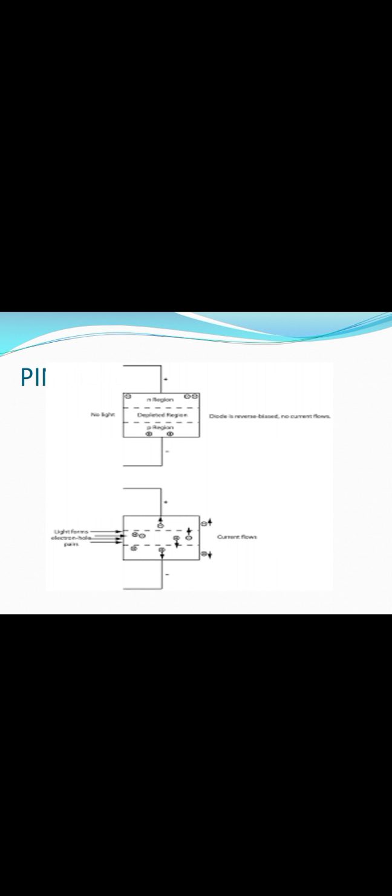The type of semiconductor material and the energy of the incident photons determine the penetration of the incident light. This is analyzed with the above circuits, looking at the 0 to 63% rise time of these junction diodes. The photodiode should have a capacitance of a few picofarads or less. To get a low capacitance value, the surface area of the diode should be small, with good coupling, and the area is not reduced below the core of the attached optical fiber.